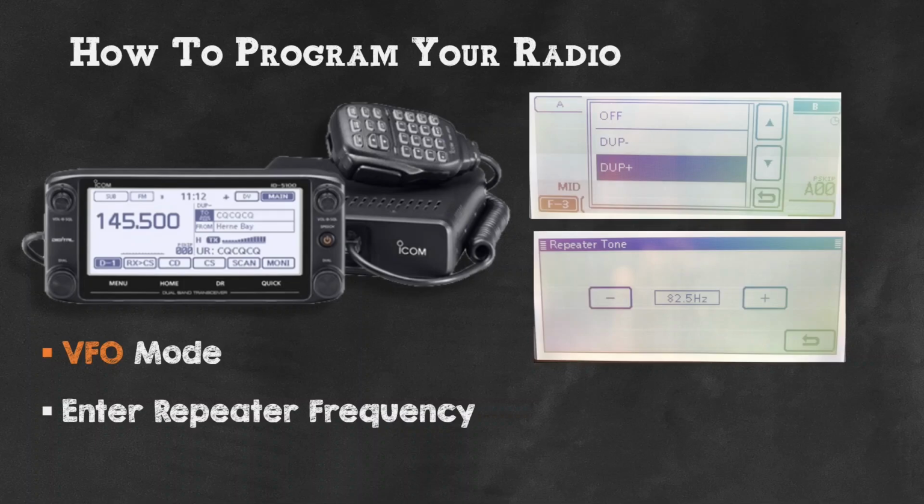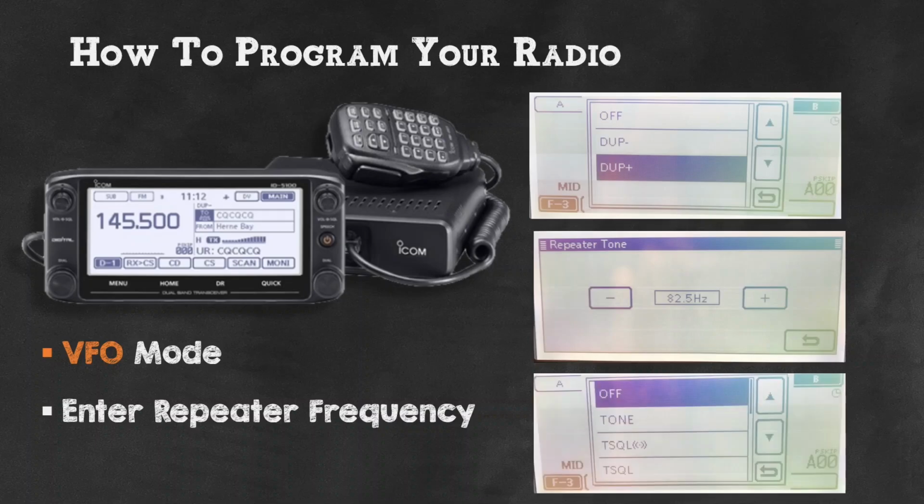I just scroll through on the repeater tone. It's all pre-programmed. All of those possible repeater tone possibilities are in the Icom software. And here's where it gets into 9 out of 10 times, tone works. 1 out of 10 times, it's going to require me to select tone squelch. So it is separate. Most of the time it defaults to this. But if you can't be heard, go back to your radio and change it to a tone squelch.